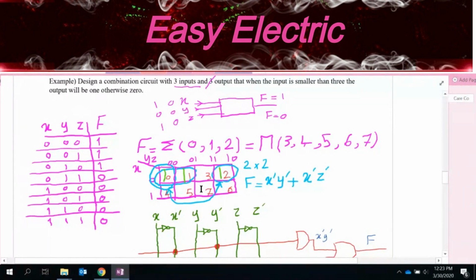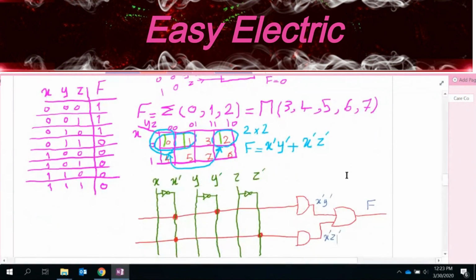Then find the new sets, which again, the number of the sets should be minimum, their members should be maximum. Then if you write the corresponding sum for each of these terms, you end up with the simplest form, but this simplest form should be in the form of the product of sums, okay? So it shouldn't need more gates than what you use for this form. It should be almost the same.